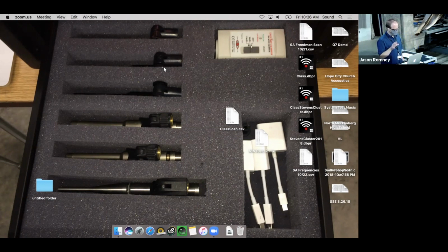And the idea behind a source-dependent measurement system is that it still compares two things, but what it's comparing is whatever you captured from your microphone or your audio input, and it's comparing it against a sound that it knows it created. So it creates the sound that then it listens back for and compares against. And it's a very known and predictable sound that it makes. And so because it knows exactly what it created, it can tell right away the difference between that and what came in on the mic.